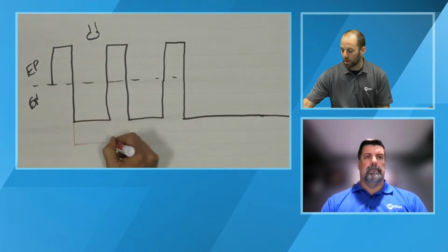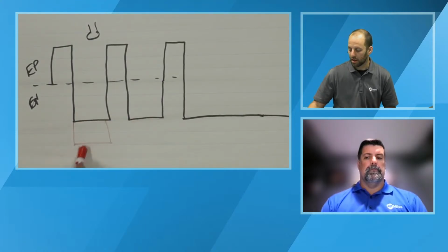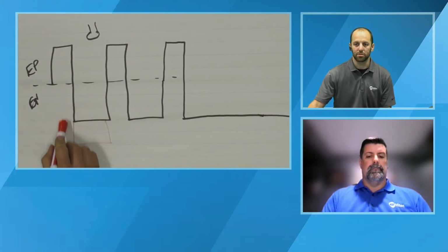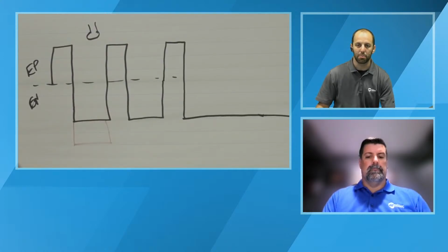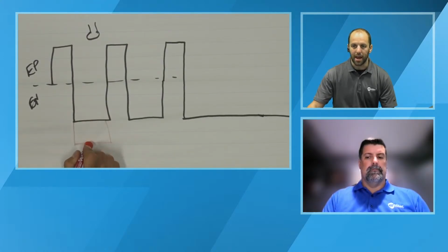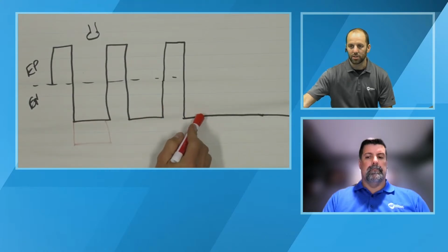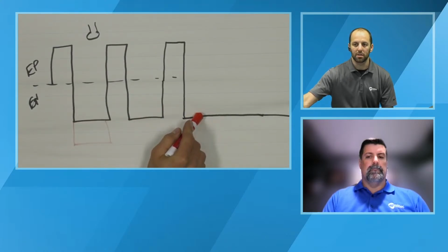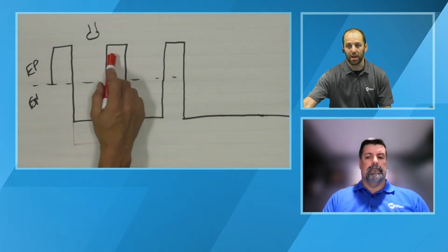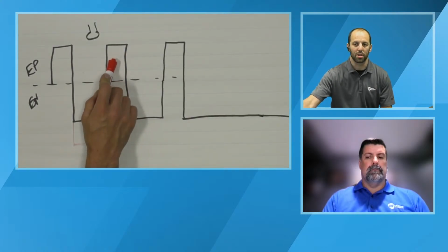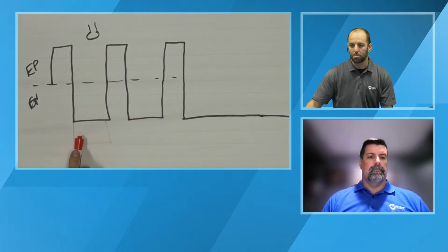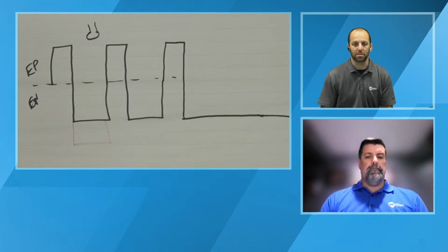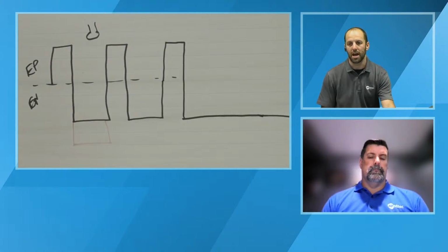So utilizing that independent amperage, again, amperage drives penetration. This certainly would help get more heat into the workpiece, because now you don't have these periods of time where you're putting heat up on the tungsten, but we can largely accomplish the same and get the same results without adding a new variable and more confusion for the operator, simply by using what we already have in the machines.